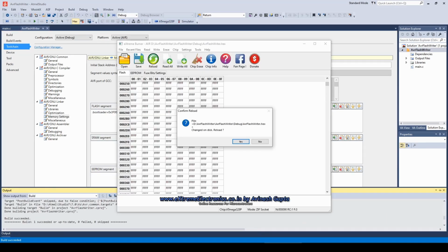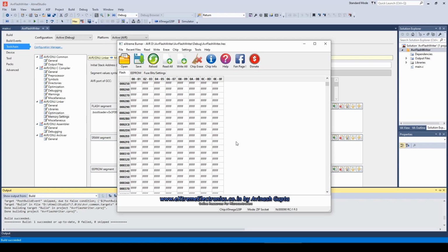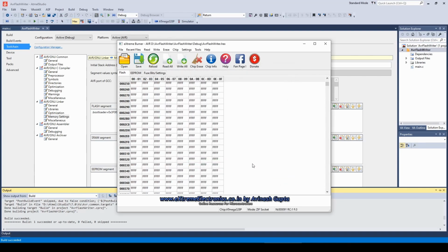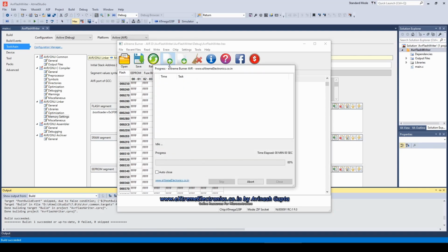We will do a reload in our burning program, and then we write again. We can immediately go and read things back. And now the display of the burning program is going to reflect whatever is on the flash memory. And we are looking at what is about to happen at the target area of hexadecimal 300.